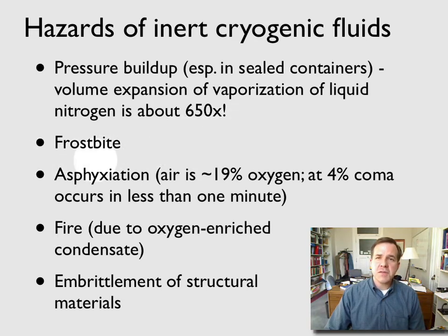A second hazard is frostbite. Obviously, cryogenic fluids are at very low temperatures, and if they are splashed onto your skin or into your eyes, there's a possibility for significant tissue damage by frostbite. Asphyxiation is also a potential hazard. If you release a large amount of inert gas simultaneously, it will displace oxygen from the atmosphere, and if you displace enough of the oxygen, then you can pass out very quickly, much more quickly than you might think.